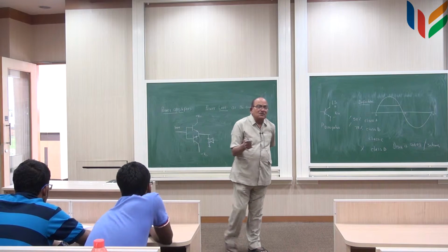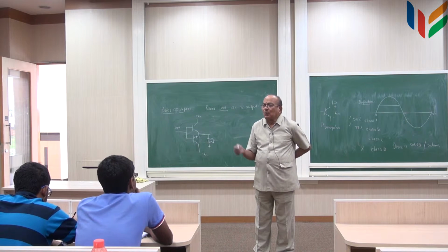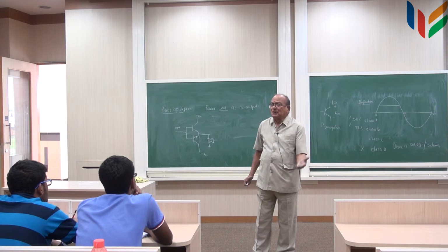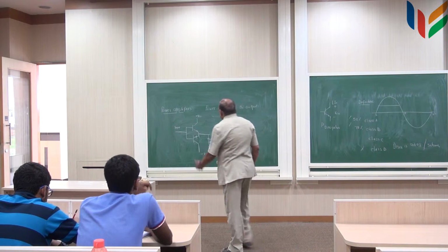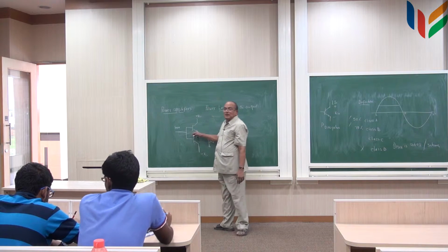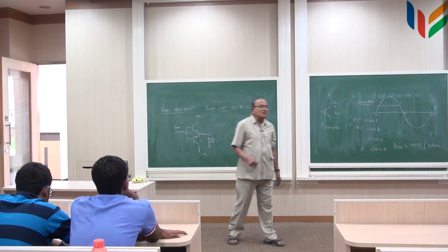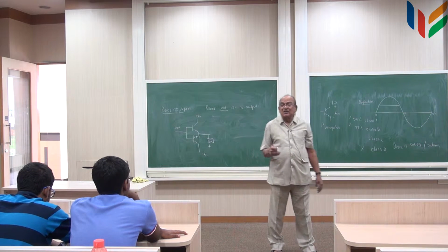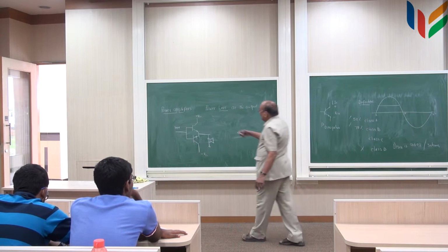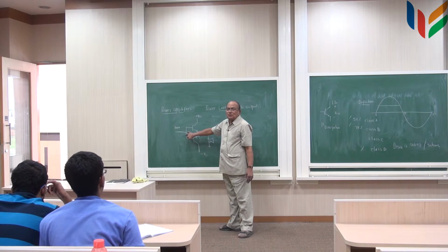For power transistors, this value is not even 0.7, it goes to in terms of 1 volt or 1.5 volt or something, because of more silicon sitting inside. So typically maybe around 1 volt or more than 1 volt. So what does it mean to us? It means that if the VBE conducting is approximately 1 volt, this will not start conducting until this amplitude reaches 1 volt.